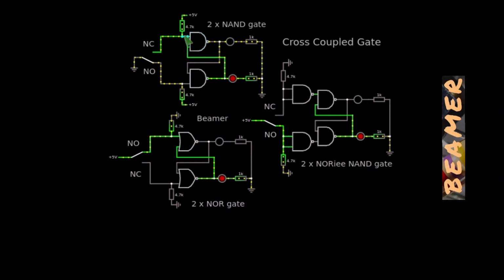Well, the other input to that NAND gate is pulled up and is not taken down to 0 volts, so you've effectively got a 1 there and a 1 there, the output of which then, because it's a NAND gate, is a 0, and the 0 is then transferred through to the other input of this NAND gate. So you can see this system is locked.